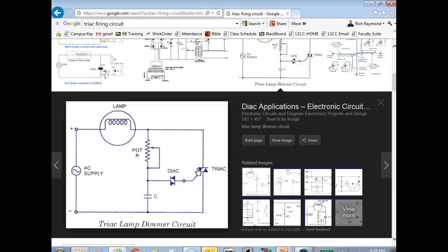So these solid state devices can become leaky, but another thing that can happen is they can short, and your motion detectors and everything are outside, so they're in a pretty harsh environment. I've seen them short, I've seen them open, and you break them apart and see the triac and the diac in there. It's really neat. It's not much to it, and they're not real hard to fix. But that's back when they used to cost a pretty good deal of money.